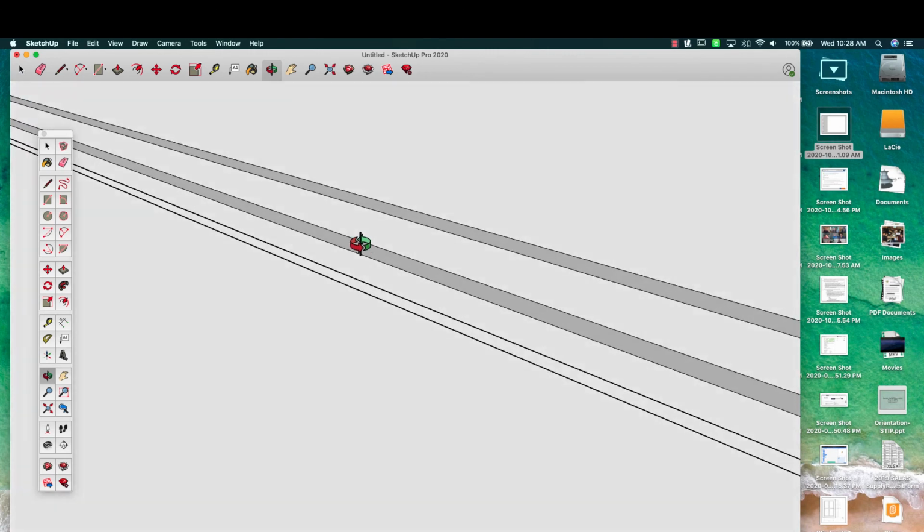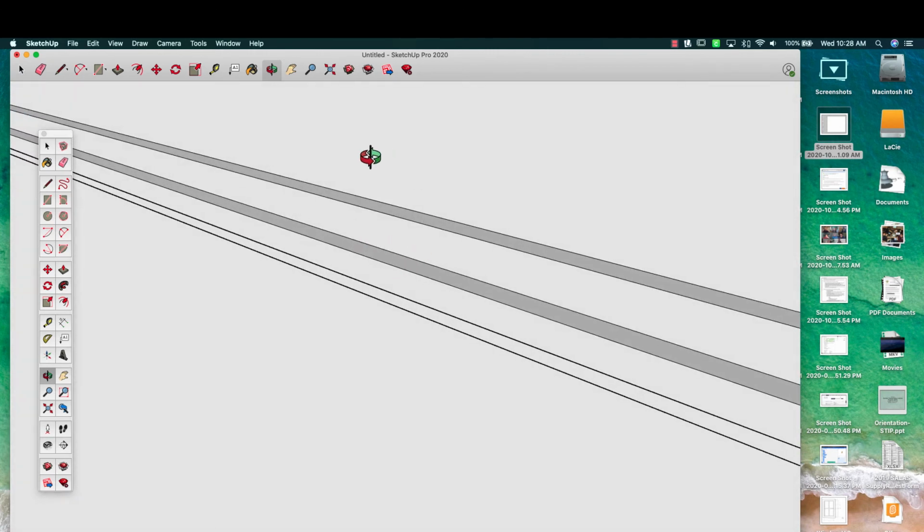It's very important that you zoom in, because as you can see, I need the guideline from this edge, on the face of the wall. But I could easily by mistake take this edge, and then my guideline is going to be outside of the wall. It's not going to be on the wall, or I could choose any of these. So very important that you choose this one.